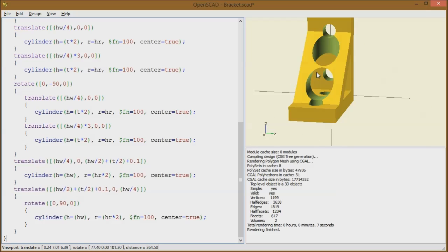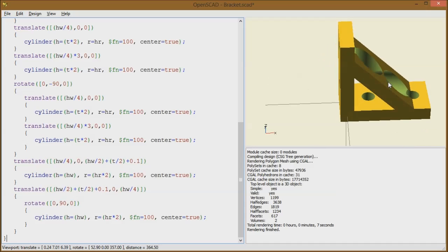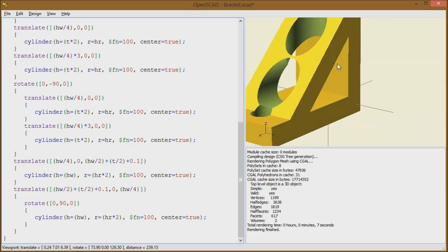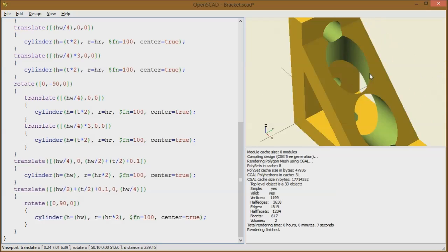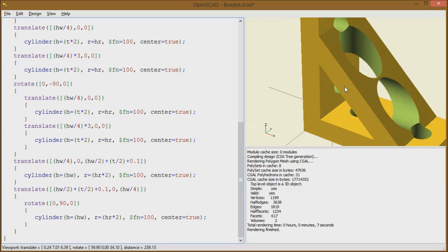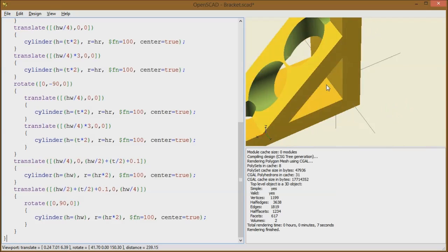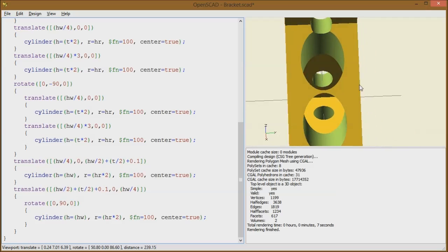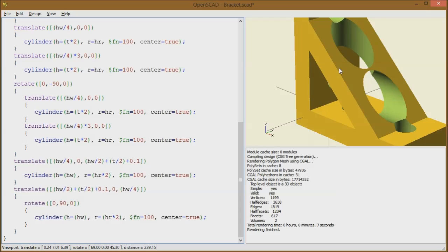So there's a couple of issues with this still. In the next session, what I'd like to do, as you can see here, this little center bit here is extremely thin, right? So if you try to print that, it would either droop or just not work in the first place, because it is a minute little piece of plastic. As I said, try to make all your pieces of plastic at least 3 millimeters thick, unless you have some of the commercial printers, they might be able to go to that resolution fairly well. But for home-built 3D printers, parts that thin are going to start getting a bit dodgy.